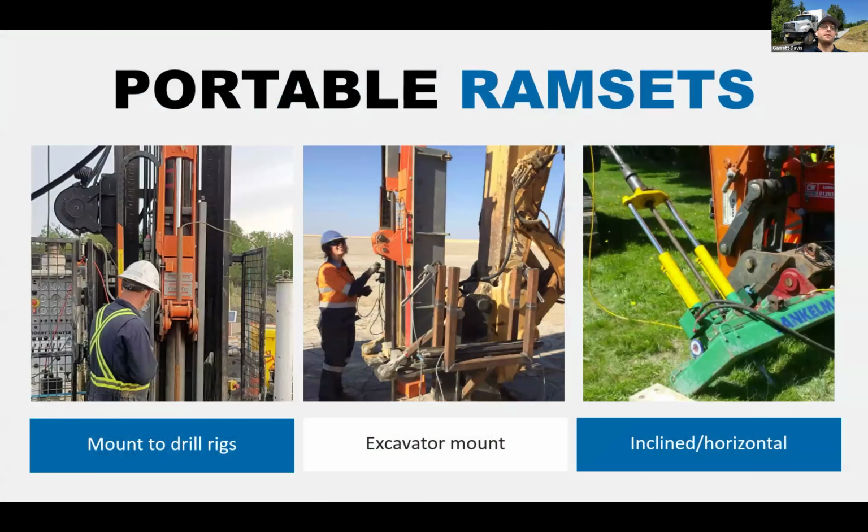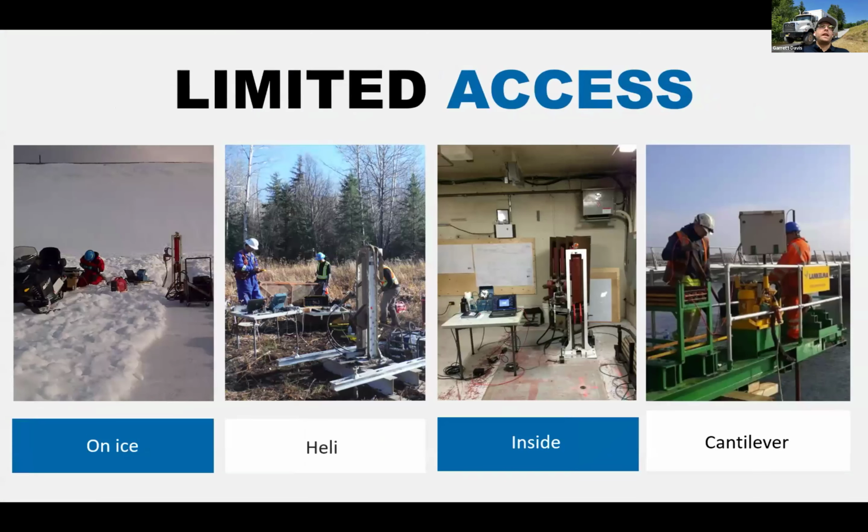Also portable ram sets. They can be mounted to drill rigs, sonic rigs. They can be added to an excavator mount to push vertically or even inclined or horizontal pushing. And there's limited access ram sets, smaller, more portable ram sets that 2 people or 1 person could move around. They can be brought into basements, bolted to concrete slabs. Out on a lake, they can be anchored into the ice, and you can test those lake sediments down at the bottom without needing to get a boat or barge out there. You can even use them on cantilever setups.